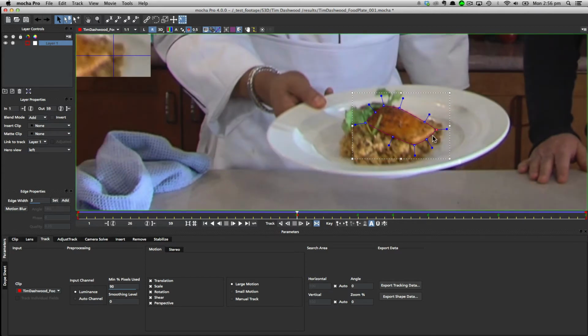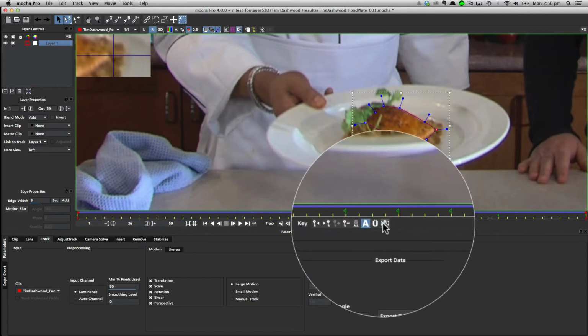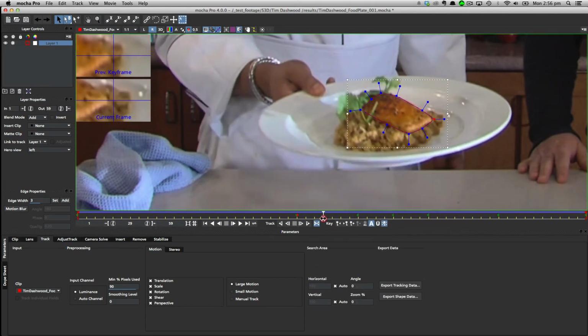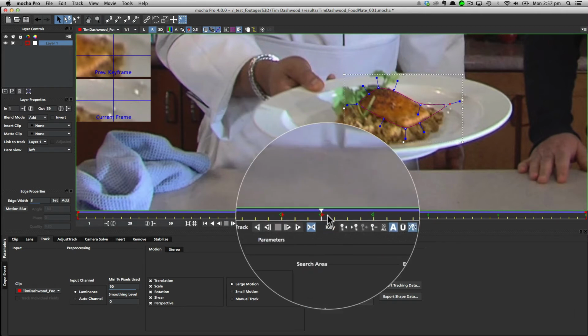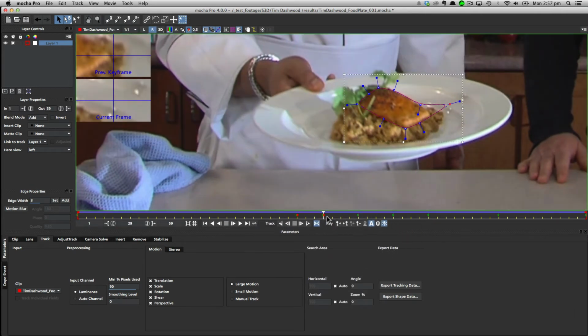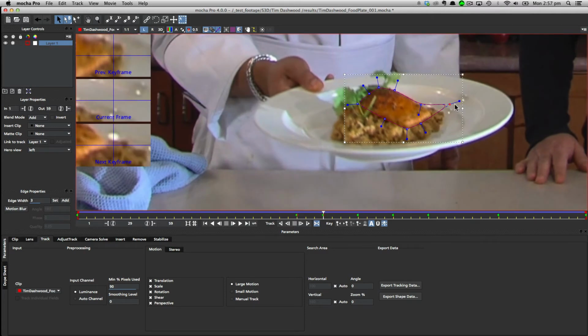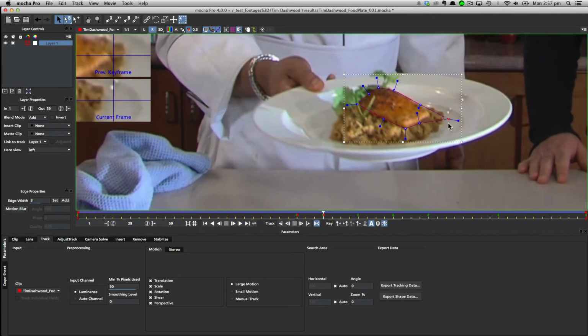Finally, if you want to modify across both views at the same time, you can use this Apply Keyframe Changes to All Views button. If I switch to somewhere else in the timeline and now move this control point, you'll see it generates 2 keyframes for left and right, and it's actually changed it in both views. And if I modify it in the left, it will happen in the right, and if I modify it in the right, it will change directly in the left.